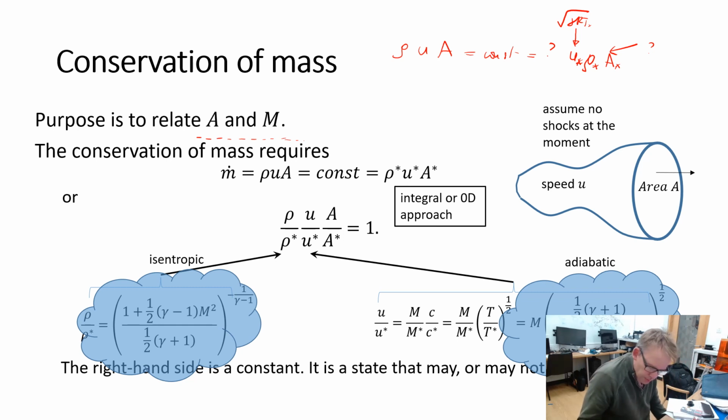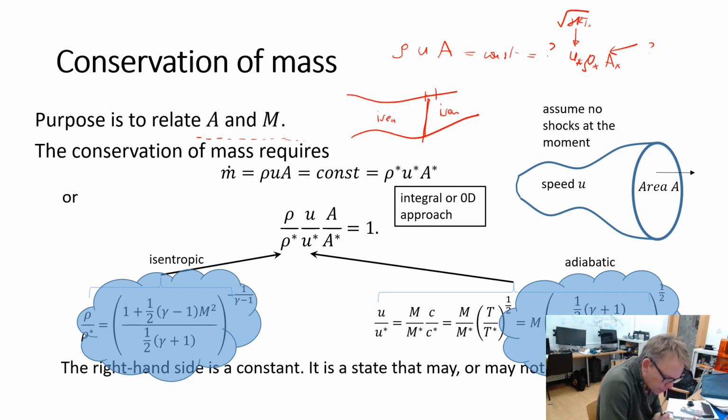Now we're going to assume that the flow is isentropic. Reasonable assumption. If we do have a duct flow and we do have a normal shock, then the flow is isentropic here and it's isentropic here, but it's not here. So even this approximation can be used quite generally in places where shocks occur, but not across the shock itself. So before and after are pretty okay.